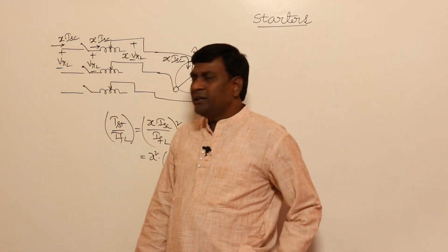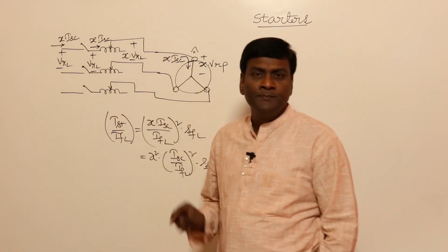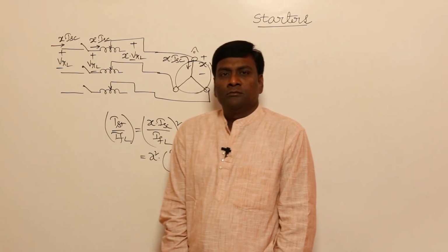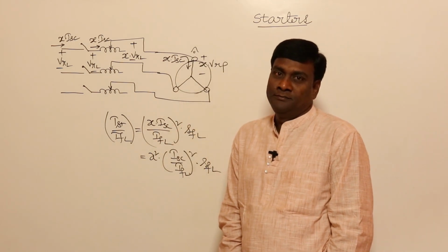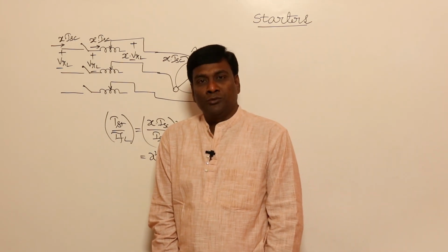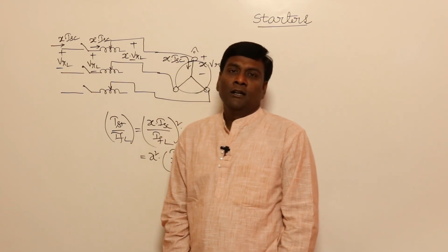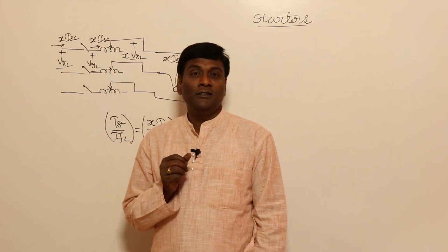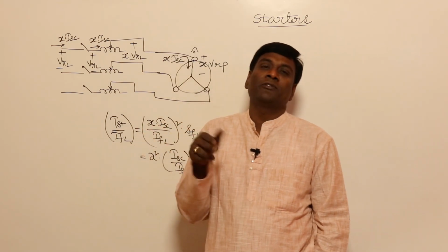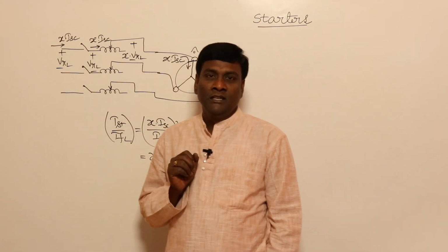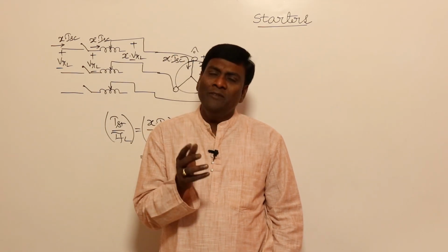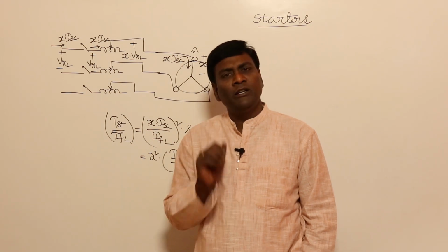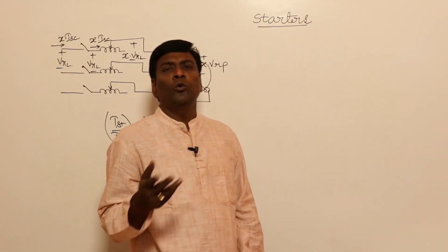Now the point here is, there are two things. The first interview question is, do you prefer reactor starter or resistor starter? Which is better to use? Now you may think that resistor starter is lossy, reactor starter is lossless, so let us prefer reactor starter. That is wrong, because we are not going to play with the machine. For example, if you go to a farmer, what will he do? He will switch on his motor and go and do his work.